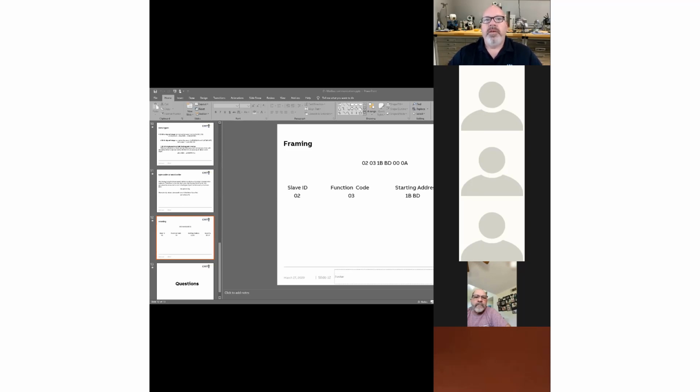Now these registers are going to be 32-bit, meaning that each register is 32 bits in size. You can have registers that are 16-bit in size. So I could change this and say, no, these are all 16-bit registers, but I still need to add them together to create a 32-bit float.